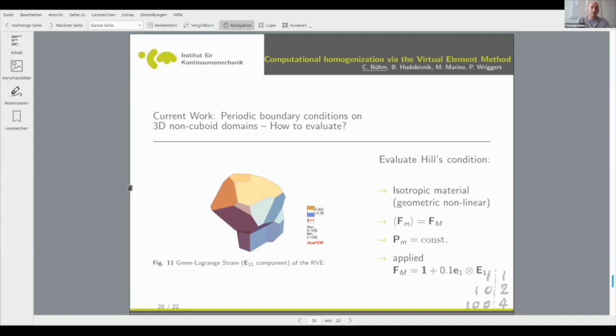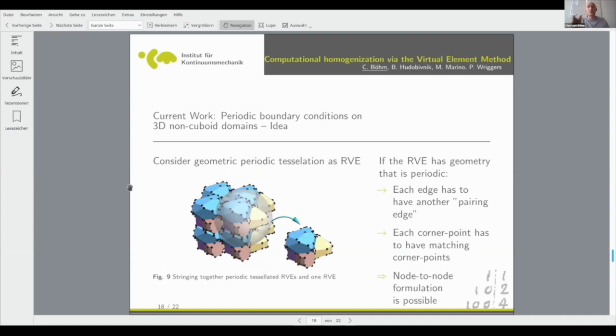So this works, and the great advantage is that contrary to FEM, where you would have to mesh really fine and use either linear displacement or uniform traction boundary conditions, here, without any pre-processing, except adding these 5 nodes, which is not a big part, you can easily introduce node-to-node periodic boundary conditions, which is great for your convergence in a two-scale scheme. And also, you have no additional pre-processing, which also fastens your routine.